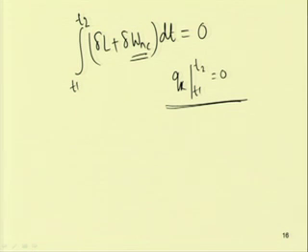unlike a discrete system, the equation of motion is a function of both space and time. In case of a continuous system, the displacement parameter is a function of both space and time. In that case, to reduce it to its temporal form, as we have already discussed, we can use the Galerkin's method, the generalized Galerkin method.